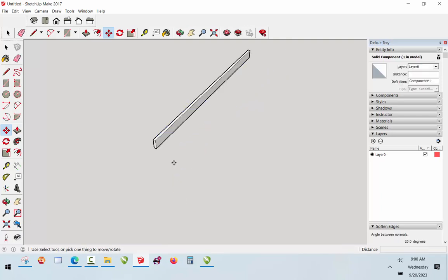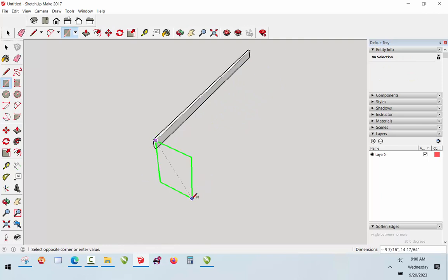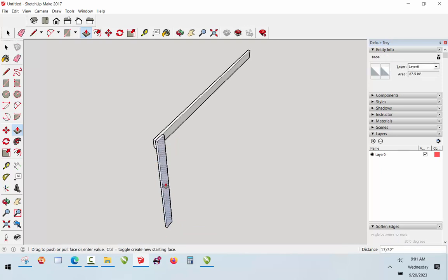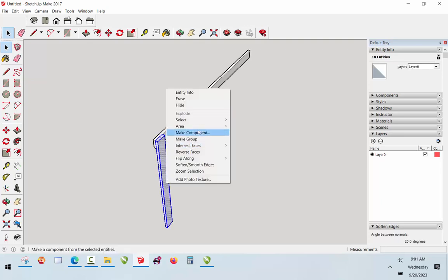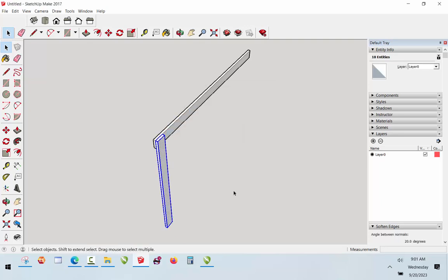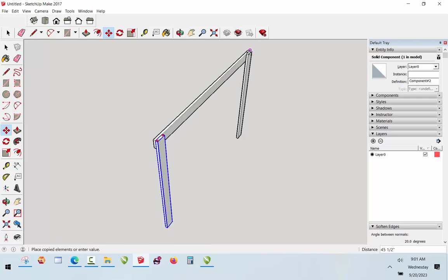So anyhow, now I'm going to draw my leg, and I know, again, I got to switch to the right plane. There's the right plane. So my leg, I know, is 2.5 inches wide, and it's going to be 35 inches long. The reason it's going to be 35 inches long is because this customer wants a 36-inch tall table, and we can get two 35s out of one fence picket. So we're going to go ahead and copy this leg down to this side.